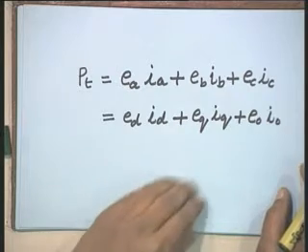It has some merits which have been discussed in literature, but it has some demerits also, and that is why in most of the models which have been developed, the DQ transformation discussed earlier is used, where we use KD and KQ equal to 2 by 3.